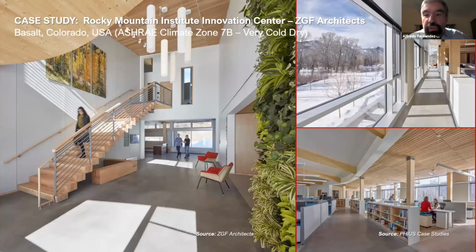Here you see the smaller photographs on the right show the circulation area provided near the south-facing windows, which creates a thermal buffer zone. Through the addition of the lower bookshelves, these bookshelves serve as partitions, but they also reduce glare on work surfaces when solar radiation is coming through the windows. By contrast, in the lobby area, where we don't perform visual tasks, we have solar radiation absorbed directly by the floor slab, and a very vibrant and open space where solar radiation contributes to the heating of it.